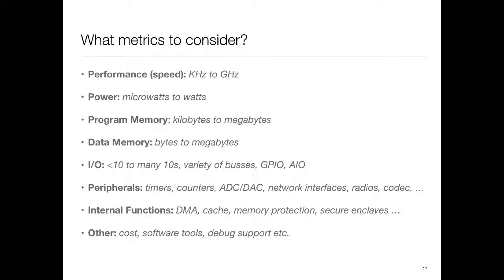A lot of ARM processors have something called TrustZone. Essentially, what TrustZone does in these embedded processors is give you a normal operating mode and a secure operating mode. If you switch to the secure operating mode, anything running in the normal mode has no way of accessing it. Or at least that's the theoretical guarantee they seek to provide. So lots of things are happening on this side also.